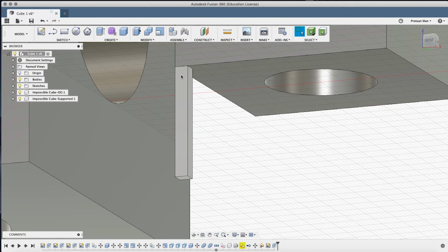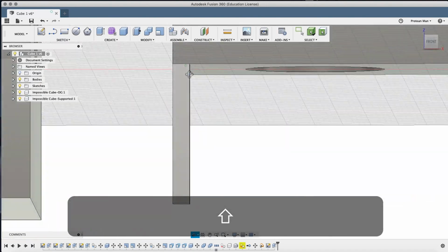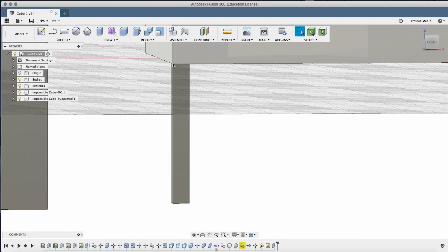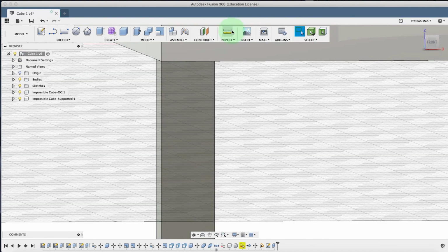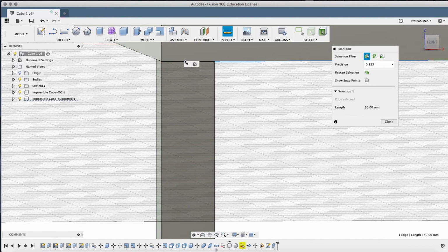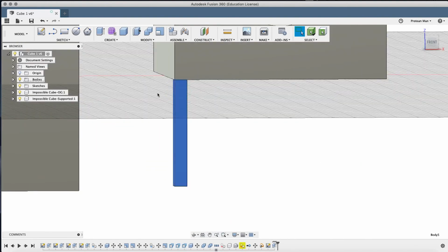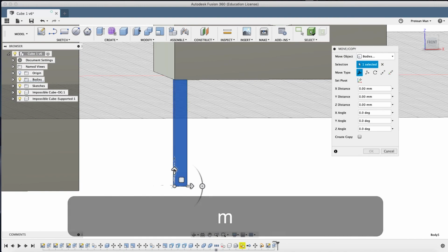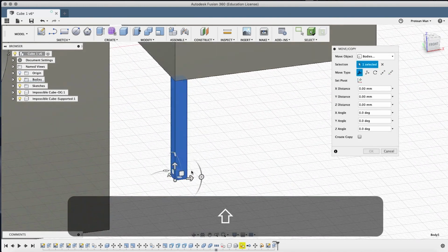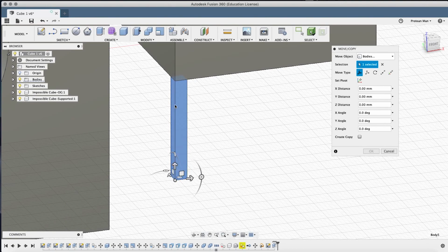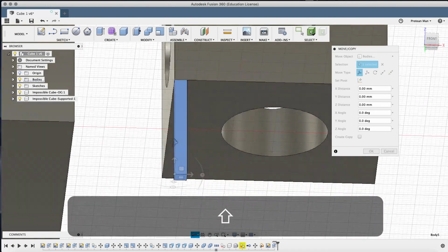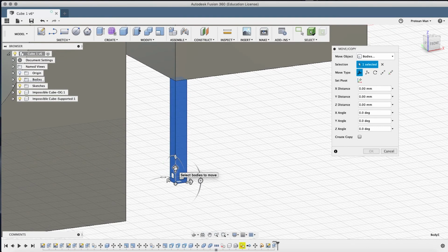But right now I'm going to think about 3D printing, because if you know anything about it, you know that this distance here, which is pretty much 0, if I measure it, it's 0 to 0. It's really, really close together. There's no distance. We actually have to remove this. So now I'm going to click my new tower. I'm going to hit M to move, and then on one of the arrows, there's a whole bunch of arrows and options that pop up. Get the arrow that's pointing up the tower, the vertical axis, the Z axis. Click that arrow. We're going to move down.